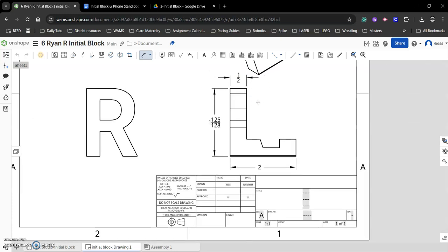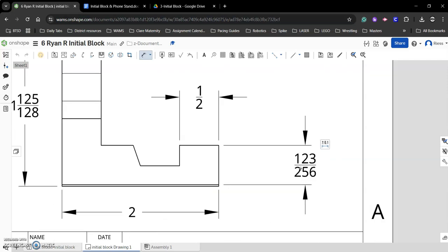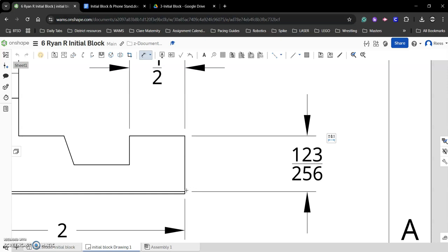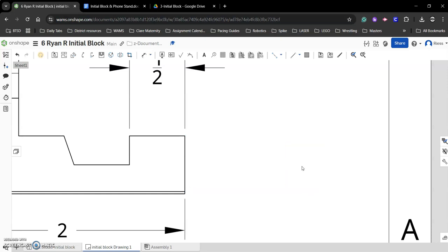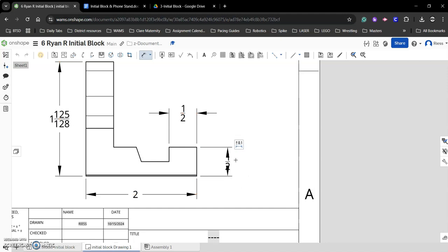Width of that. We'll go here, boom. That should be a half. Here to here. Again, it could be a little wonky, especially since here I'm going from there, so I could certainly just double check if you have a weird part, right? So I'll go from the top. You might have to zoom in a tad just to make sure. There you go. That's good to go. If you ever have dimensions like this, if you hover over it, see I have an arrow there, I click on it, it puts the arrows on the outside so you can see the dimension. Game changer.